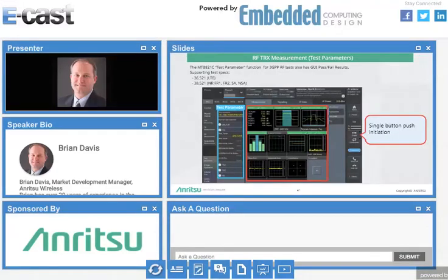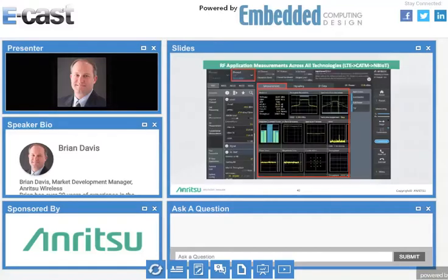And there's the single button push. So instead of going and changing parameters there on the left, you just go through, say what tests you want to run, what conditions, what subparameters, and then single button push, and you get pass-fail results for each one of those tests. And then they're showing in the GUI, if there were issues, there'd be a fail, and then what type of measurement. So we have this for LTE, NR, FR1, FR2, standalone, non-standalone as well.